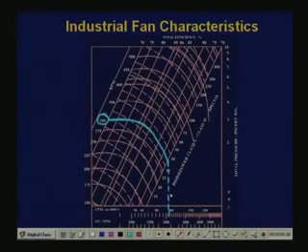Now you see what the power requirement is here. Look at these curves. This is the constant 30 curve. This is the constant 40 curve, 40 horsepower. So where are we? We are at 35. Now what happens when you are at 80% flow?